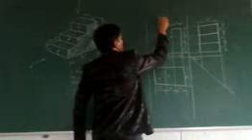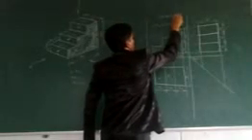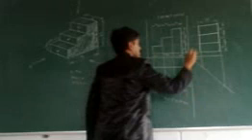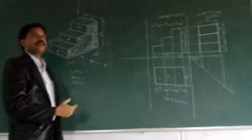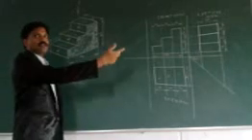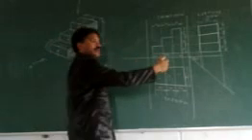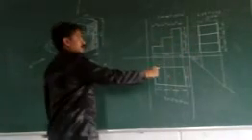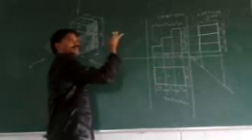And this one is the front view, and the top view, and this is the left side. This is a very simple method to obtain any side, either the left side or the right side. If you want the left side view, project these lines towards the right side of the front view. If you want the right side view, project these lines towards the left side.